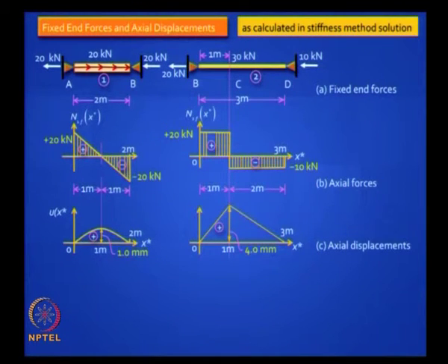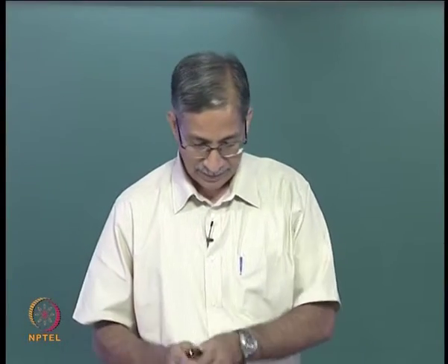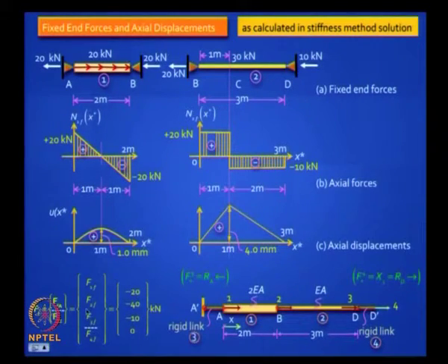Okay, now this part you have to borrow bodily from the element stiffness method, because there also you need this. So remember, we've done this, you have to find the fixed end forces, and after you've done this you have to figure out what the fixed end force vector is. So you look at these results and then manually you have to figure out what F1F is, what F2F is, F3F and what F4F is.